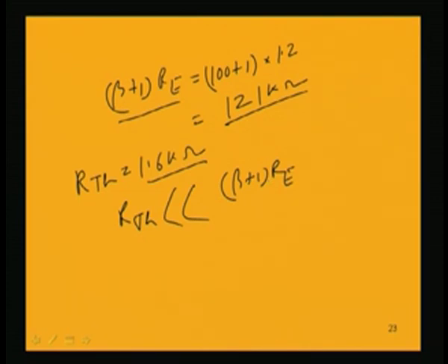That is why the potential divider biasing scheme, or voltage divider biasing scheme, is used very popularly in transistor amplifiers. Mostly this potential divider biasing scheme has advantages over the other biasing schemes that are already discussed, like the different variations of emitter bias, such as collector emitter feedback bias.